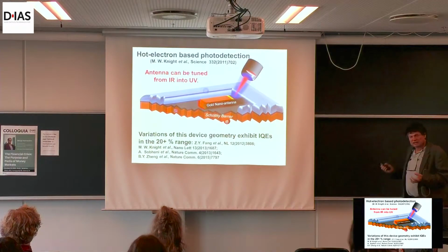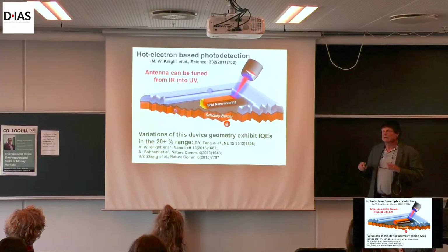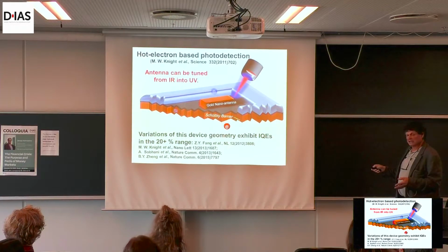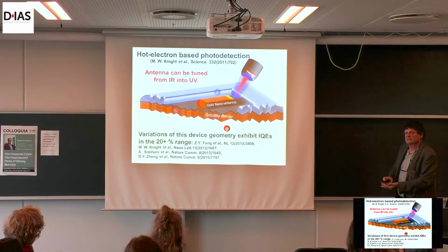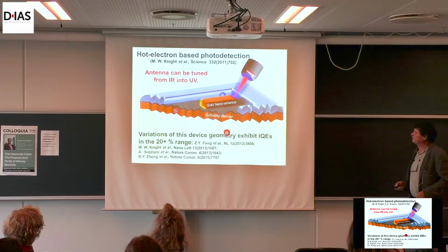This kind of hot electron-based photodetectors can have a quantum efficiency of 20%. They are not limited to the band gap. Although we use silicon here, we are not doing an excitation from the valence band to the conduction band. No, we are doing direct injection in the conduction band.